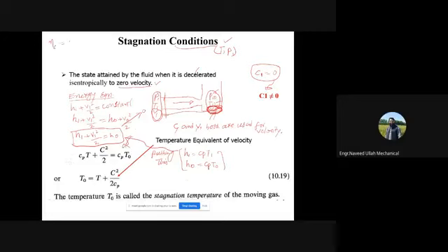That was the work consumed by the compressor when the process is isentropic, so T2s minus T1, divided by the actual work, T2 minus T1. Cp cancels out. The ratio of these two is your isentropic efficiency, right? Now, what are this T1, T2 and T2s etc.?